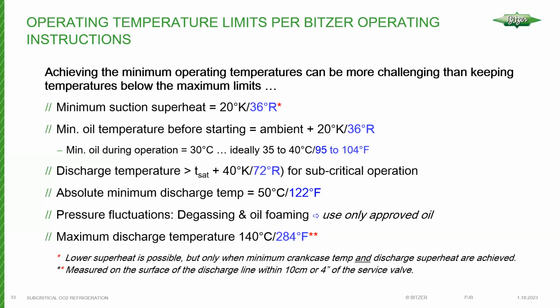When you're measuring discharge temperature, by the way, for checking discharge superheat or for the minimum or maximum discharge temp, always get as close to the service valve as you can, within 3 or 4 inches or so. Make sure you've got good contact and even insulate the sensor. Get a good reading.